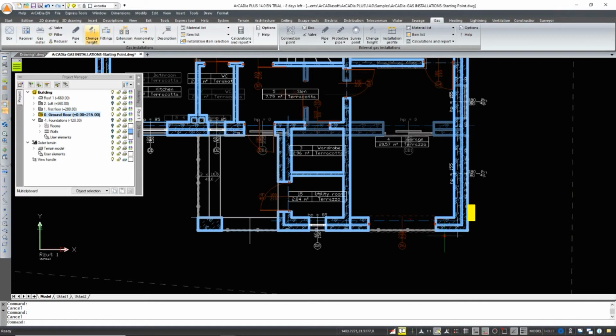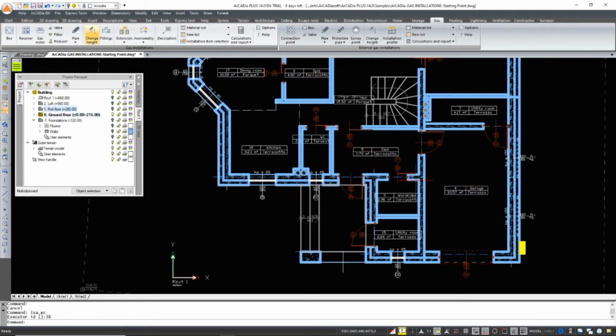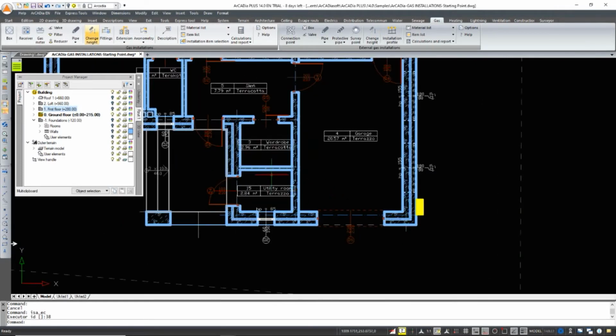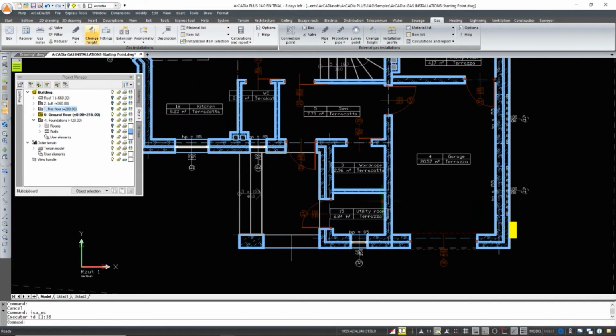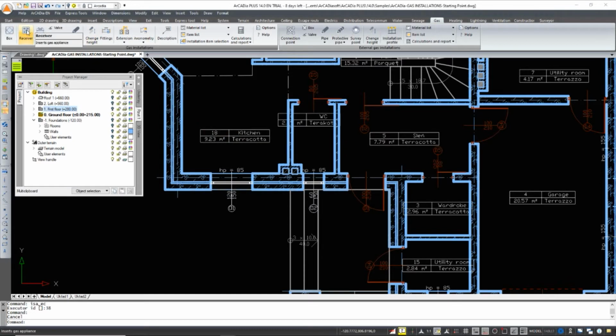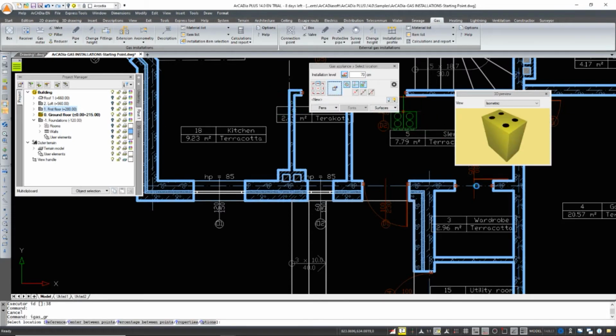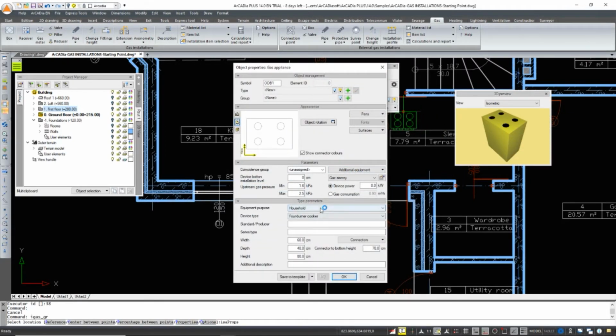The gas box is the source point. The installation can be made from any point, or we can also place the devices in appropriate places. We can insert a gas stove in the kitchen. The receiver will be here. After inserting the gas stove, we can set its parameters, select the type of device, producer, type.